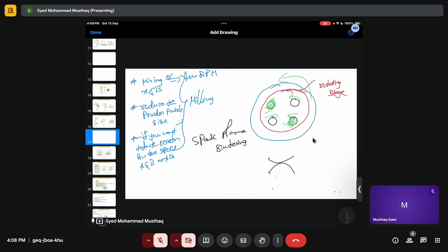A green pellet is nothing but you apply pressure. So you create a die. Simple. You have a die. It has a hole in it, and you put a stopper here, and then you pour powder, and then you apply pressure from this die, which can be done either by hand or just a pressure valve. Okay, so you will have a pellet.